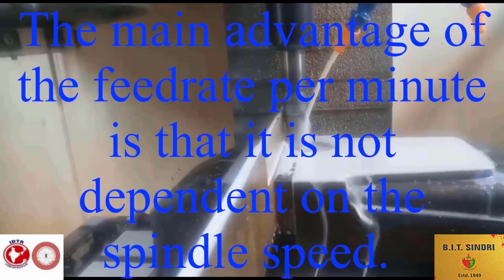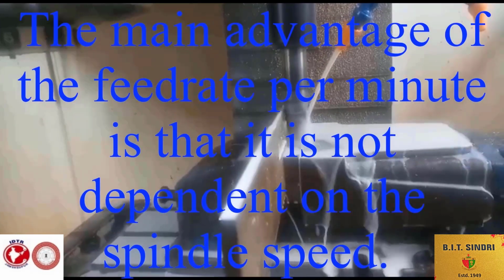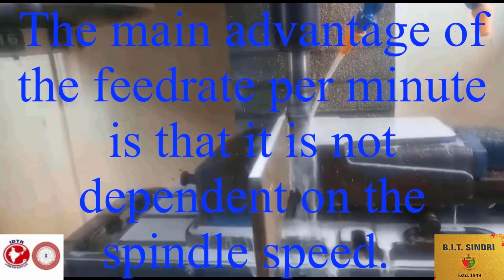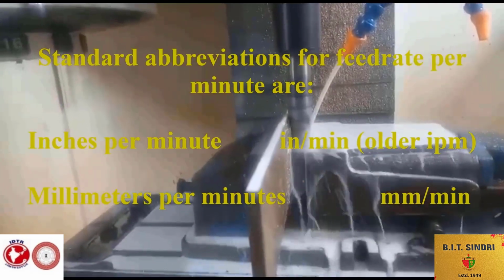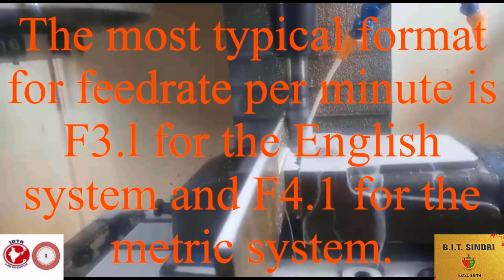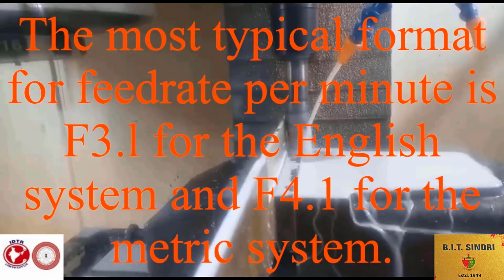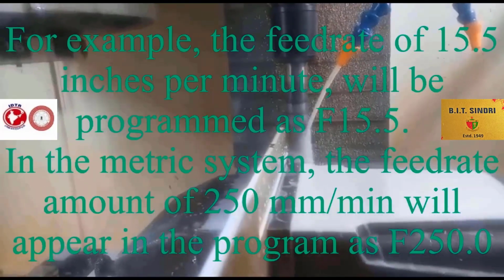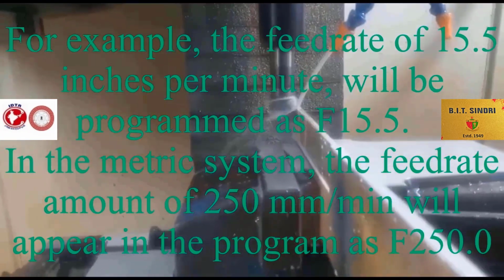The main advantage of feed rate per minute is that it is not dependent on the spindle speed. That makes it very useful in milling operations using a large variety of tool diameters. Standard abbreviations of feed rate per minute are inch per minute and millimeter per minute. The most typical format for feed rate per minute is F3.1 for the English system and F4.1 for the metric system. For example, a feed rate of 15.5 inch per minute will be programmed as F15.5.